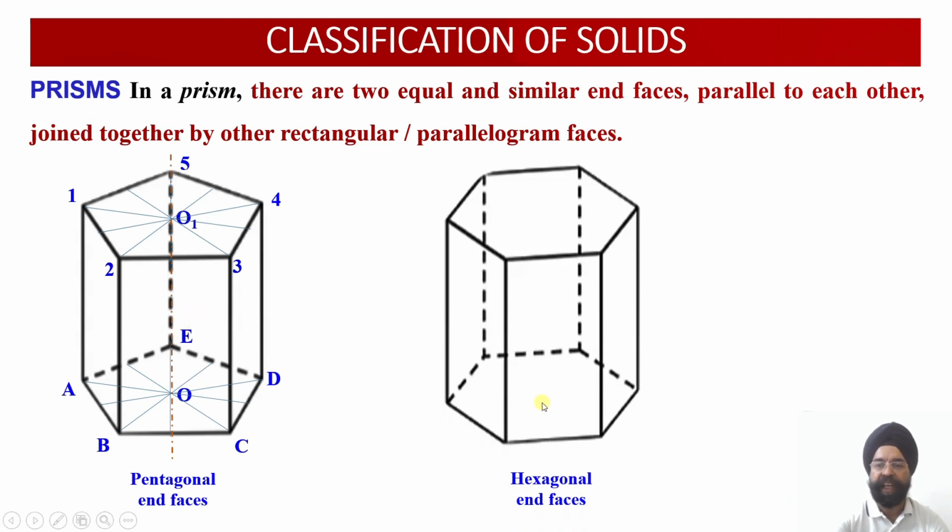Now you have the hexagonal prism. This is called hexagonal prism because the shape of the base is the hexagon, number 1. Those edges which are away from the observer, which you are not able to see, will be drawn dotted. The edges which are visible to you will be drawn using the outlines or the HB line. Now let us do the numbering.